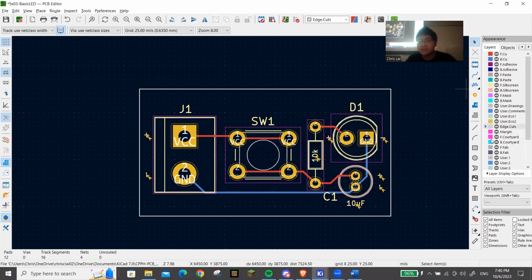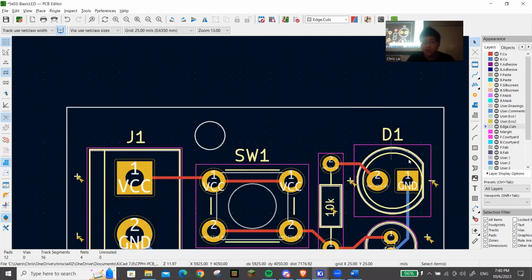So I'm going to go to edge cuts and make a circle. I'm just going to place the circle maybe right here on my PCB. Now, depending on what kind of screw you use, you need to make sure you have the right screw hole size. In this case, this screw hole is 50 mils in diameter, which is good for anywhere between an M2 screw to an M3 screw. I believe that's your options there. I think M3 might be a little bit too big, but I usually use a 50 mil diameter for M2.5 by 6 millimeter holes. Again, this is just from experience. The more you do PCB design, the more you can remember what standards you use, and then you'll be able to do projects a lot easier.